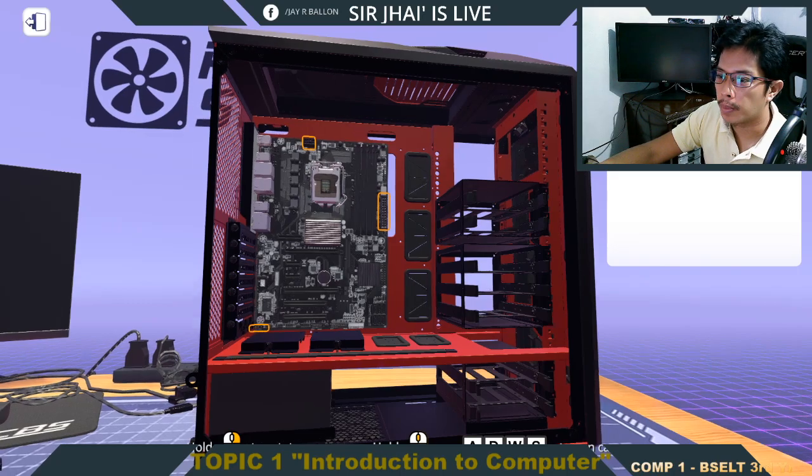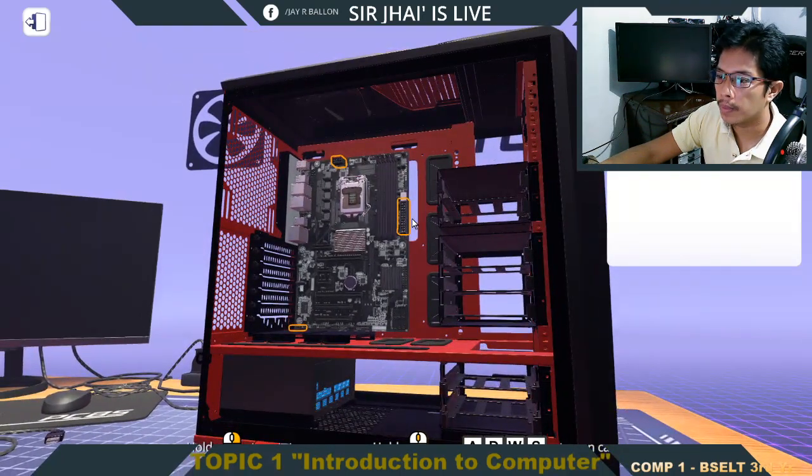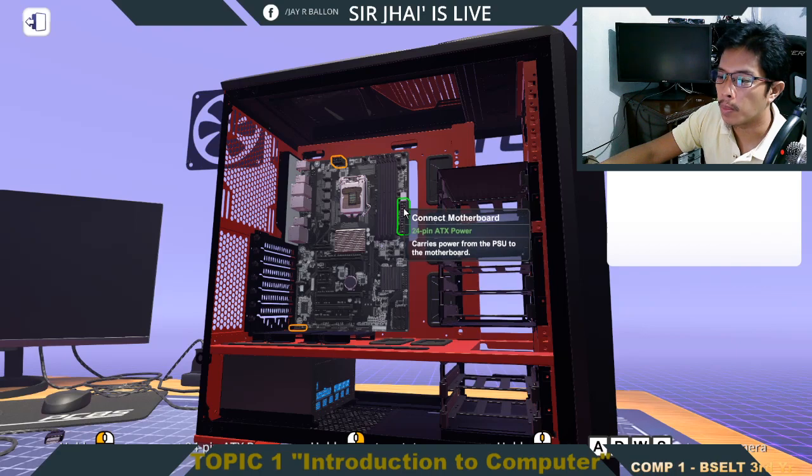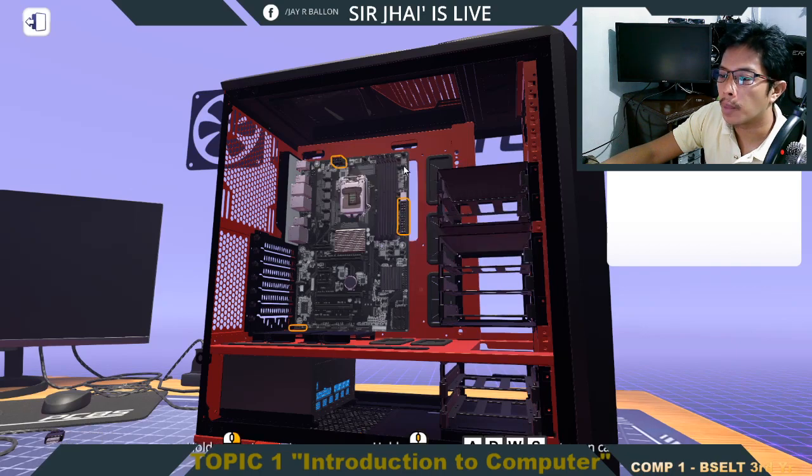Okay, so we're gonna put in now the cable for the power supply. It's a 24-pin ATX power. This is the one that's going to supply the entire motherboard. So connect it to the power supply. Yan.